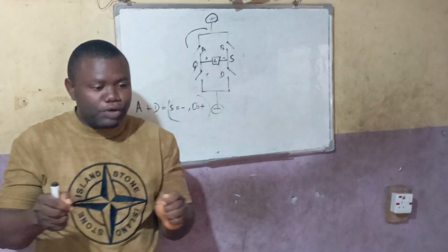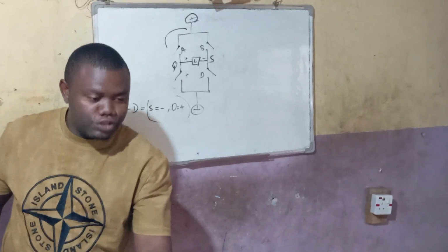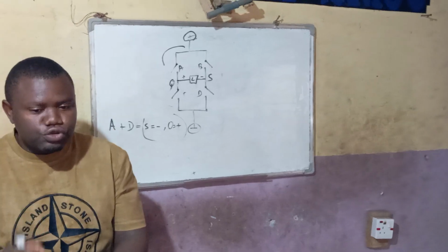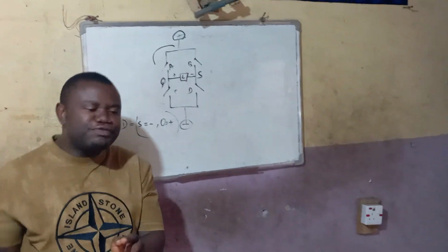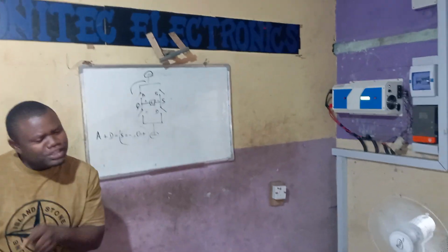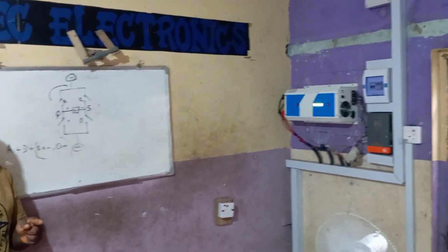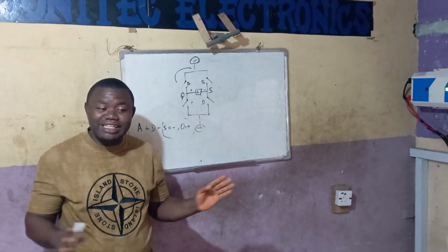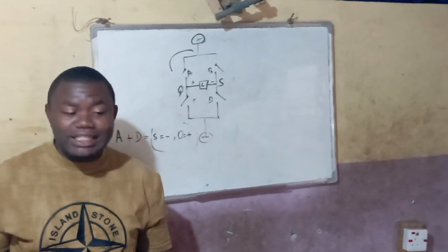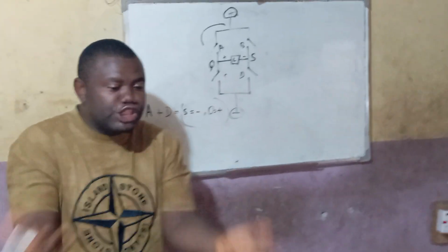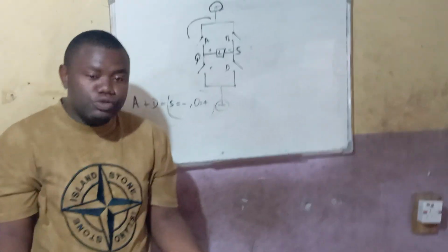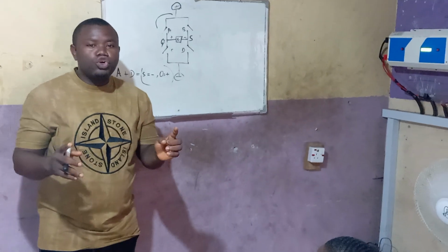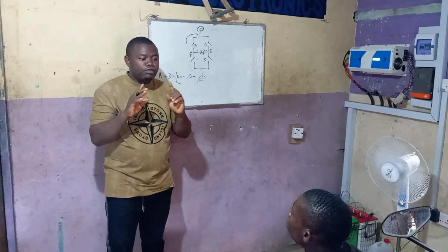Okay? You were sending positive to positive, negative to negative, and then the motor rolls clockwise. Now you want to change the polarity, you have to send negative to positive and positive to negative. The motor will roll anti-clockwise. But this only applies to motors, DC motors. It doesn't work for any other thing. If you use it for any other thing, it will destroy it.